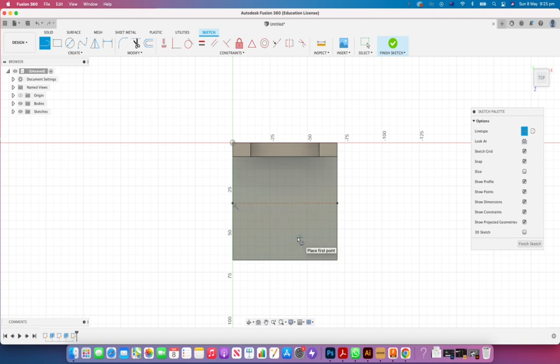So a construction line is something that you use. It might be a point of reference. It's just simply geometry that you use to get you to where you need to be. It's not really visible. As I said, we kind of use them as references. So if I went back to my drawing, I could see that that was 30 millimeters. So I've hit the D key. I'm just going to reference that from that to that edge, and I'm going to type in 30 millimeters there. Okay, so that's what we've got.